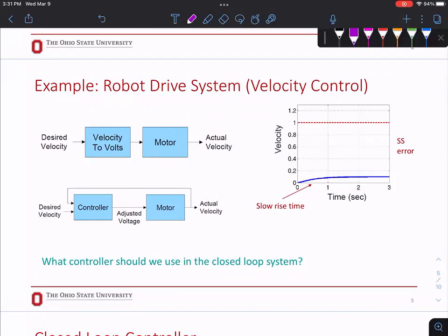That usually comes with the motor driver, so you just connect and it's good. It takes velocity or angle or RPM from you and spits out voltage. So this whole thing happens inside. Thankfully, you don't have to do it, but this is what happens inside your motor driver. But if you don't read the actual value, it's an open loop system. You don't necessarily get what you desire.